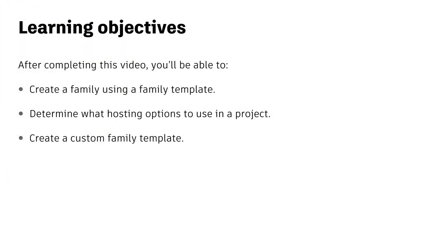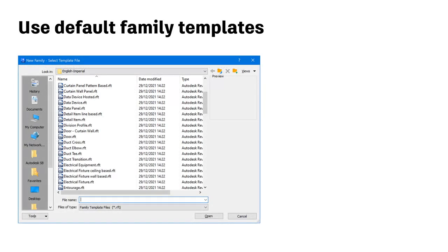In this video, you will understand how to use the various default Revit family templates and also create your own custom family template. Additionally, you will understand typical hosting options available when creating families and how to use these to create an intelligent model.